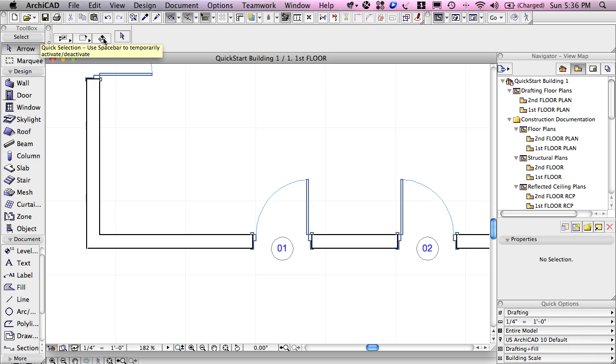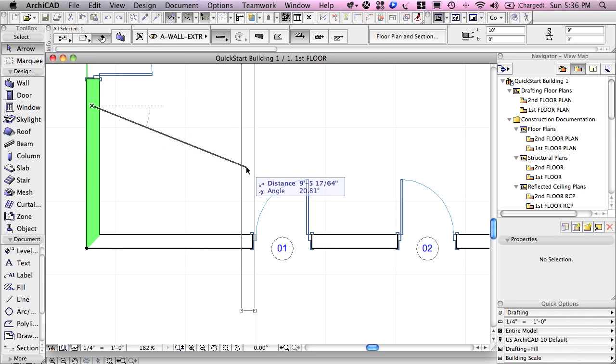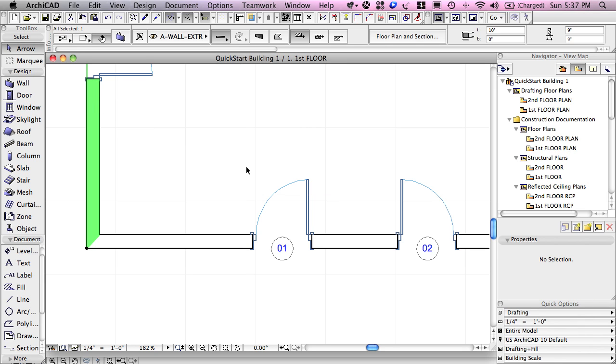So we'll be looking at this in a better context to understand it in a later module of the course, but basically having the quick selection on is convenience for most purposes, but there are times when you'll want to turn it off so that when I press down here to start to draw a box, it doesn't actually just grab this element, because in fact pressing on an element and then starting to move in one gesture is a way to drag it very quickly. So I'll just hit the escape key. Remember that escape key allows me to cancel certain things, so I hit the escape key,